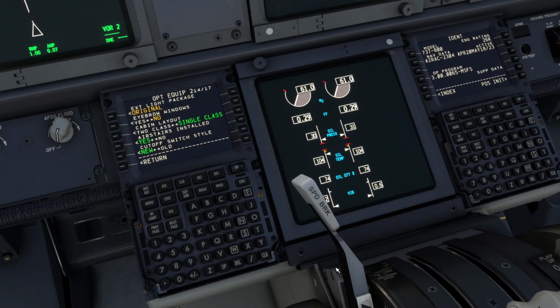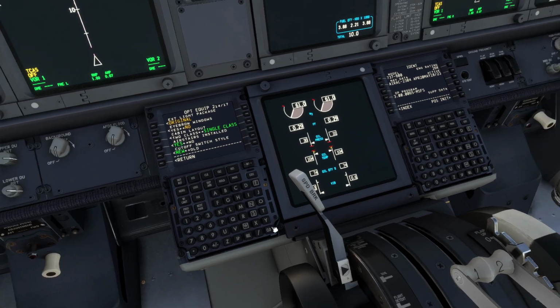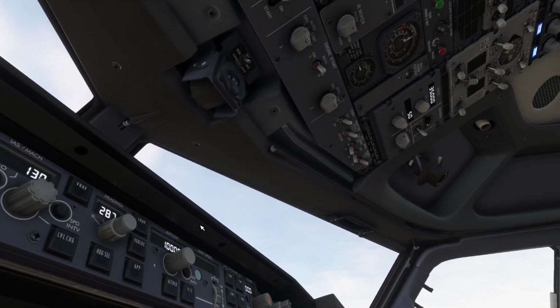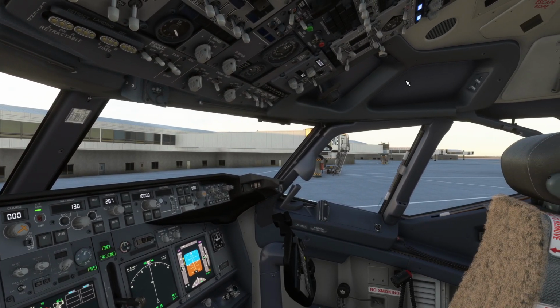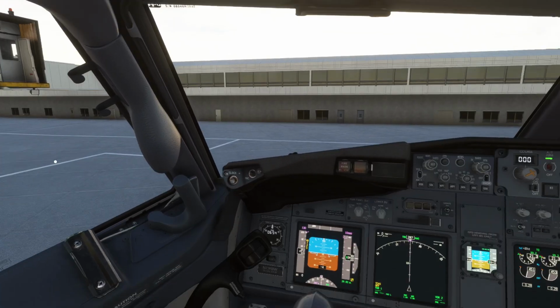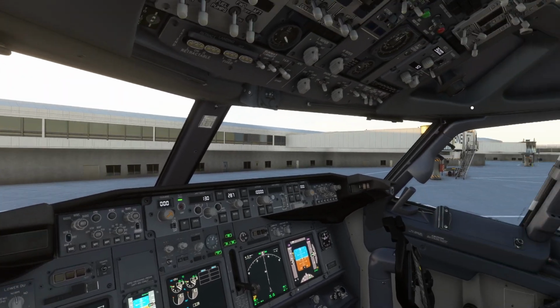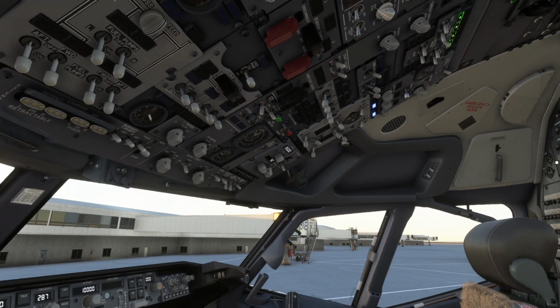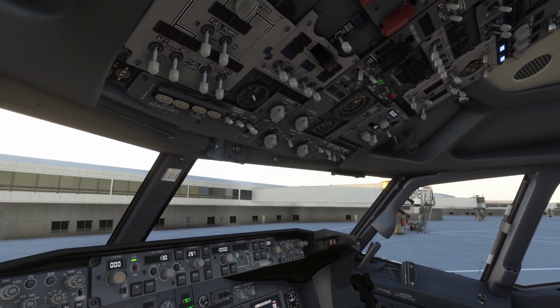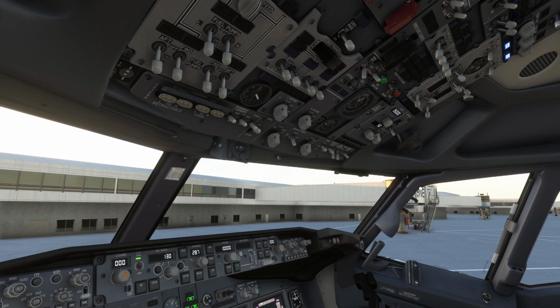Some people say that it was to help during tight turns, where the pilot sitting here and turning to the right will be able to see something through these windows. I've been flying this airplane for almost 5,000 hours and I don't really see any difference on those kinds of maneuvers. I really think that was something related to the star navigation, the celestial navigation that they used to have on the old 737s, and they just kept the same windows there until they reached the NG, and then with the NG versions they started to remove them.